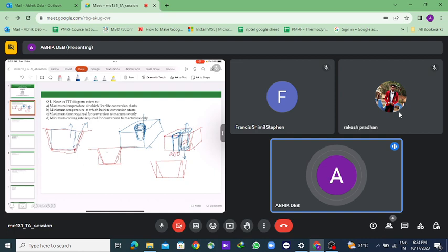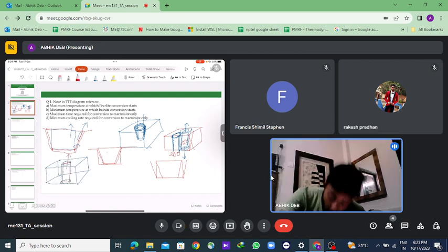That's what I'm saying. Suppose this is a hole of 80 mm diameter throughout. This is the through hole. Now the core that will be used for making this hole, you have to take this core out, right? You cannot keep the core here. So if the core is being taken out from the top, and you are designing it such that the core will be taken out from the top, then the draft will be provided like this, at the top surface.